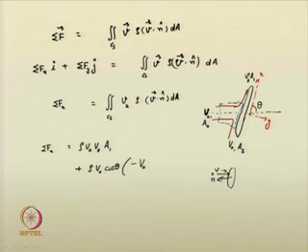So, you have a negative value. So, v 0 into a 0, then plus at this particular control surface we have rho times, now this is in the negative x direction. So, there we are already incorporating minus v 0, then the flux is v 0, both velocity and the areal outward normal vector are in the same direction. So, v 0 a 2, like that we can write.